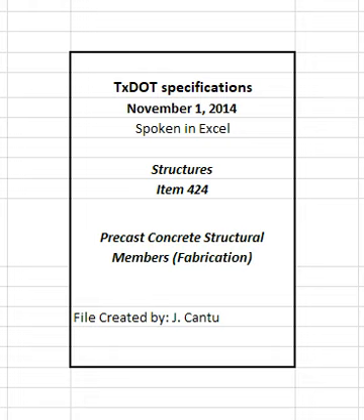Do not place concrete in contact with any material coated with frost or with material at a temperature of 32 degrees Fahrenheit or lower. Do not apply heat directly to concrete surfaces if accelerated curing is used. Take protective measures to ensure the difference between air temperature and concrete surface temperature does not cause thermal cracking. Maintain aggregates free from ice, frost, and frozen lumps.